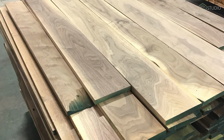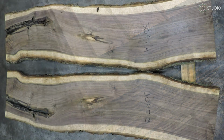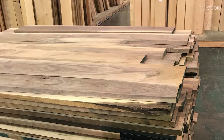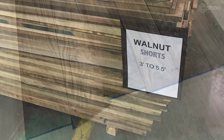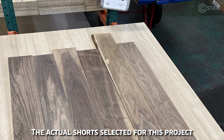Selecting boards that will blend together is an art in itself. In most cases, going to the expense of purchasing book match pieces or using a long single board of walnut is unnecessary. Hit up the short section, make color and grain selections to your liking, do quality work with the joinery and glue up, and enjoy how good walnut looks when you apply finish. The inconsistencies between different grains tend to disappear after machining and finishing.